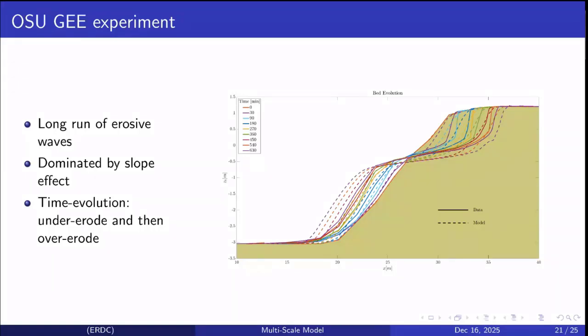And to tell you the truth, I've been struggling with this for a couple of days when I was working on it. Really struggling to understand why that would ever be. I think that it probably derives not so much from a problem with the sediment transport problem as from not including something like infragravity waves, which can be substantially significant and dominating in these really shallow regions where you have this weird shelf berm that's being developed here.